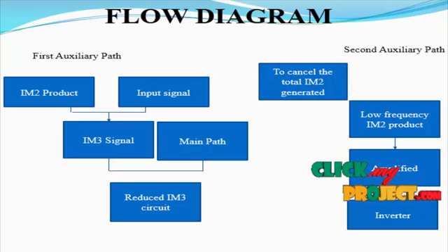The input transconductance stage amplifies the RF signal and the commutating stage switches the differential LO pair. The LO switching stage is actually a frequency doubler, which is employed to generate the even order harmonics, especially twice the LO frequency.